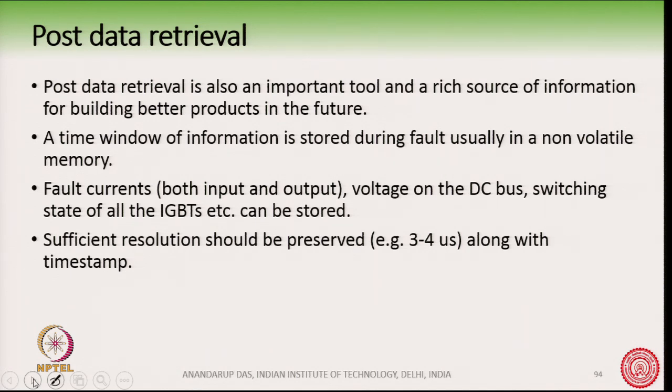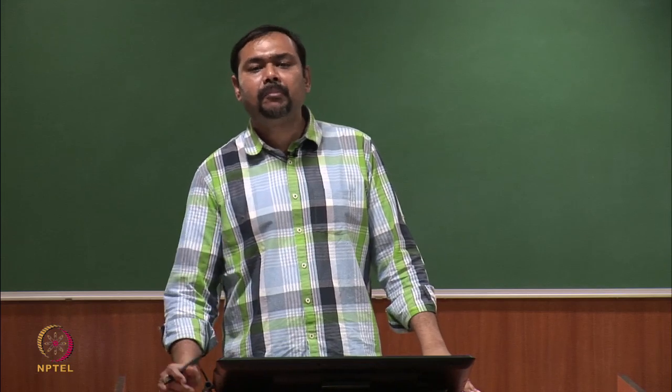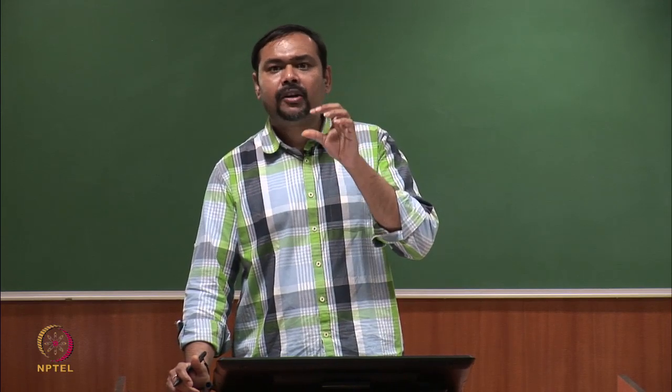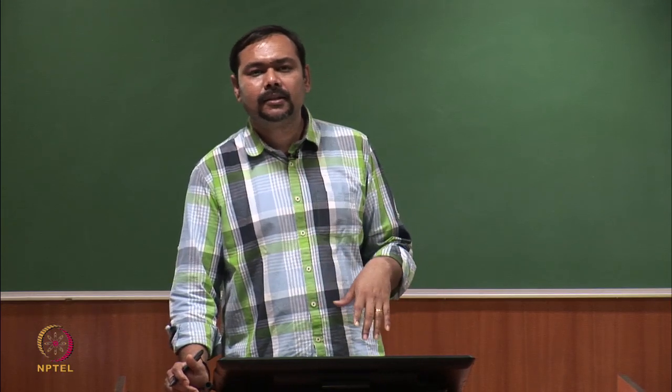So, for that, certain important variables in the converter are stored in some kind of storage, in a non-volatile memory, in the memory of the microcontroller or some kind of a board. So, this memory will contain some important variables, maybe say for the last 2 minutes or something like that. You can define a time period.